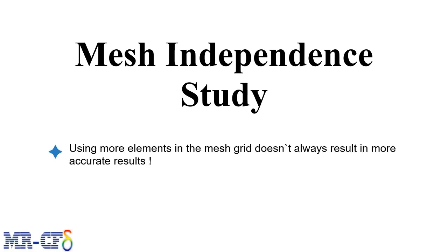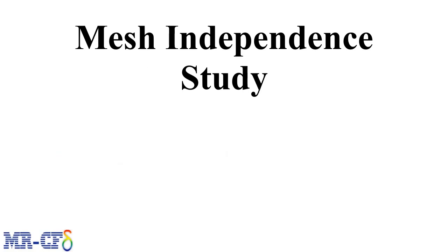Notice that using more elements in the mesh grid doesn't always result in more accurate results. The good thing is that next time a similar problem arises, you can apply the same mesh sizing. In this way, you will have more confidence in your results. The way we carry out a mesh independence study is divided into three steps.